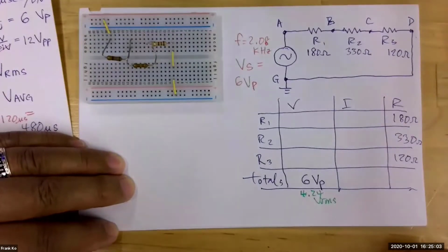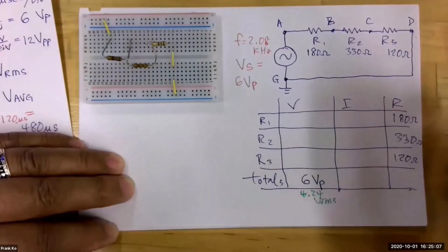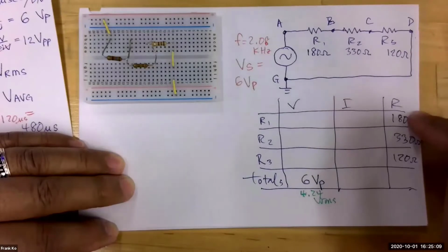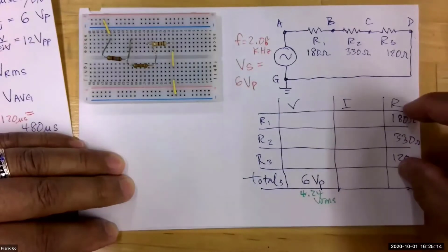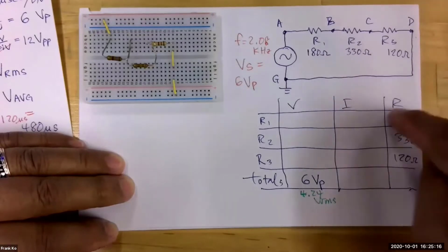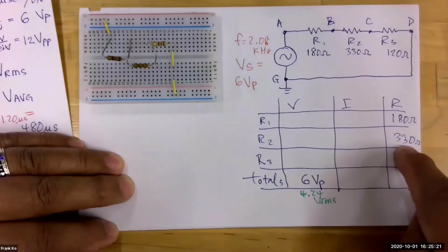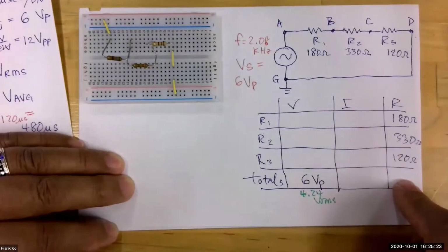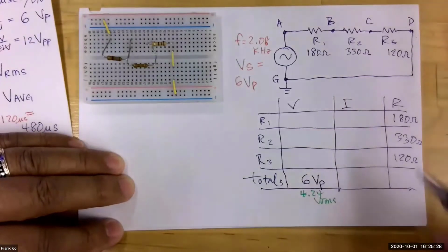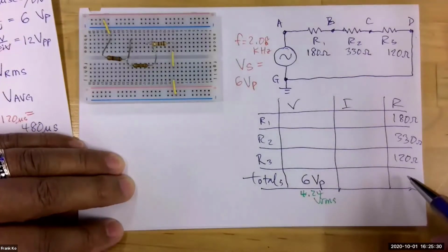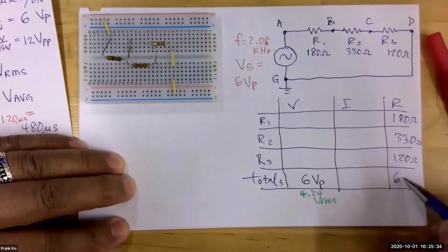Okay, let's go ahead and look for total resistance. So if we, let's go ahead and use Mama's calculator. 180 and 120. Guess what? There's a 20 and there's an 80. So they combine to give you 100. So 120 plus 180, wouldn't that be 300? And 300 plus 330, wouldn't that be 630? That's just using Mama's calculator, all right? So how many of you agree we should have 630 ohms? Give me a thumbs up. Okay, so 630 ohms.